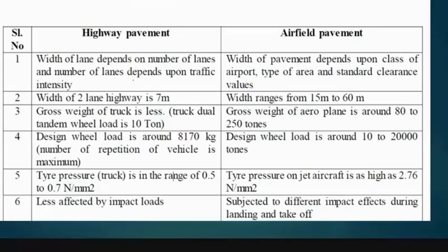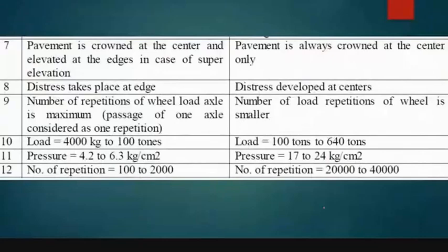It is not in terms of meters. It is hardly, say, 30 centimeters, 30 to 45 centimeters at most. It's not 0.5 meter or 1 meter, nothing like that, right? It is very costly also. You cannot build the entire stretch like that. In airfield pavement, that much thickness is only for a very small stretch where landing and takeoff take place. Throughout the runway and taxiway, a much smaller thickness is provided, as designed per the wheel load.